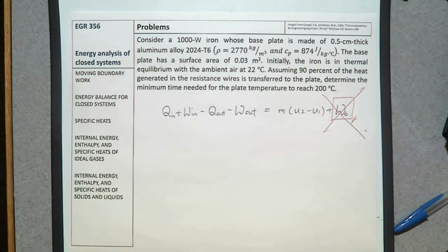I lived in Texas 10 years, and I never saw a vent on the floor. In every single house there, the vents are on the ceiling. Then why are vents on the floor in Michigan and on the ceiling in Texas? In Michigan, we want to heat. In Texas, they don't want to heat, right?